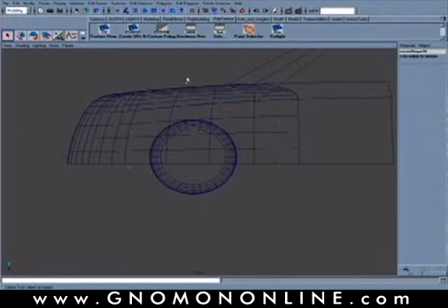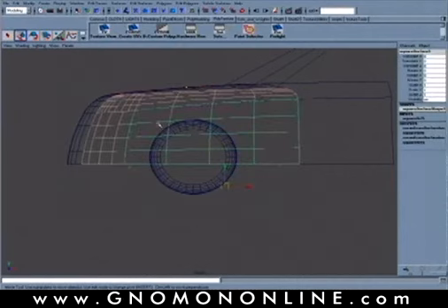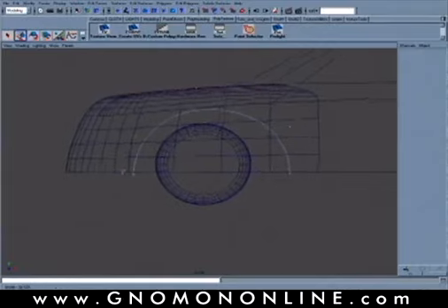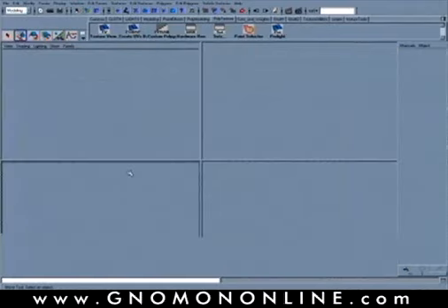Okay, and then the traditional method of just translating a few points in there. So I want to make sure this fully is inside of that overall quarter panel. Okay, that's going to give us our best behavior here. And then just kind of design it. If you want to add some more tension, you may want to add some more points in here just to create a tighter arch. This is just representing then the part we're going to come off the surface.